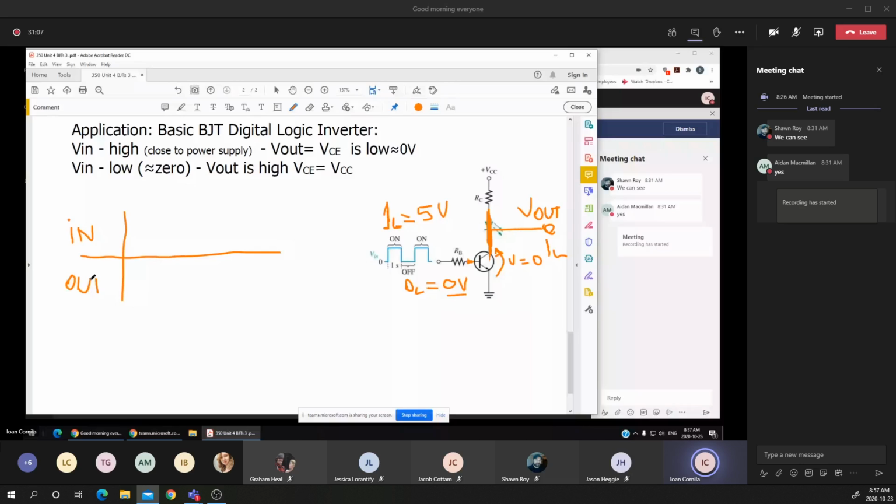And I mentioned that I'm applying a zero logic. I'll put a zero on the top, the effect on the output. If there is no voltage, again, there is no current that flows through the transistor, which means that the output, which is the same thing as the VC, remember that, the VC or the Vout, that's the output of the circuit, is at the maximum.